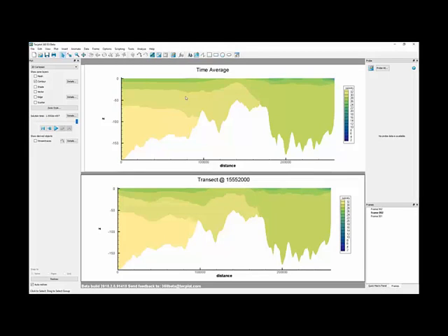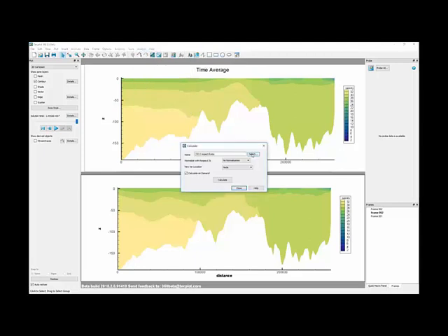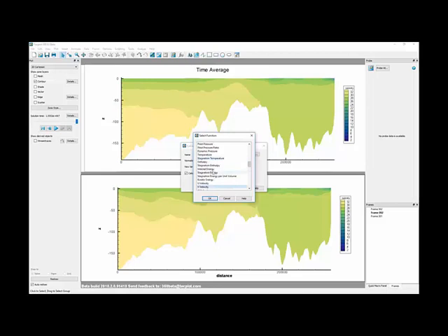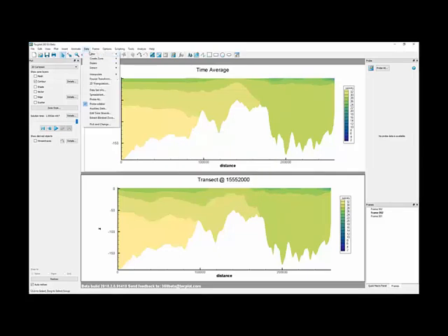Okay, well, let's say what happens if we want to look at another quantity that we don't actually have in the data set. For instance, I have my vector components, u, v, and w, but what I really want to do is look at the velocity magnitude. Well, we can do that quite easily in Tecplot. One way to do it is through the Analyze menu, Calculate Variables. This has a large number of formulas that you can execute, one being velocity magnitude, so quite easy through here. But let me calculate velocity magnitude by hand to give you a description of the equation syntax.